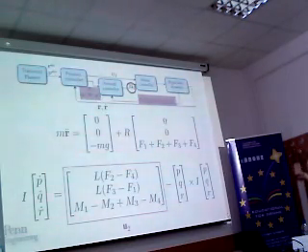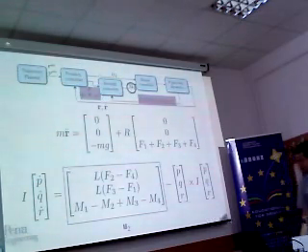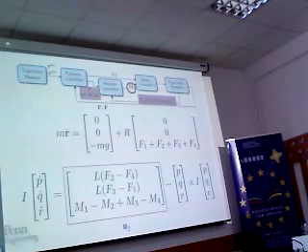So U2 is a three-dimensional vector. In the equations of motion at the bottom, we have to calculate what U sub 2 is based on the desired attitude. So based on this attitude, we can calculate the U2. We will use these parameters and the feedback in order to calculate the command U2.